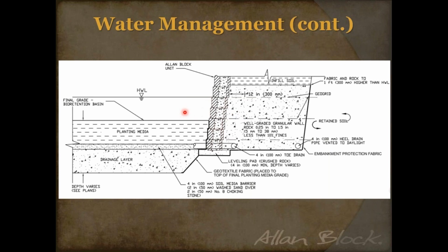What we're trying to do is, most bioretention systems do not have what they call rapid drawdown conditions. It's not like the water is going to build up and then all of a sudden it's like flushing a toilet where it just disappears. We know it's going to be a slow and steady decrease, and we know the water behind the wall needs to come down too. So water in front, water behind, that balances. The hydrostatic pressures kind of balance.